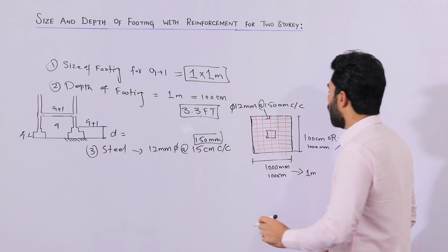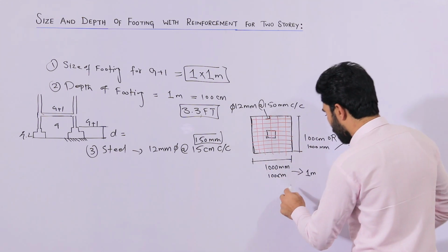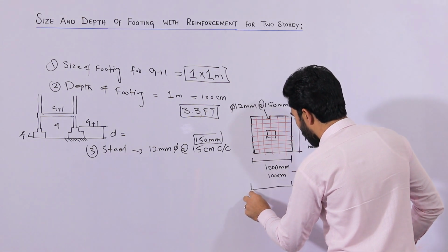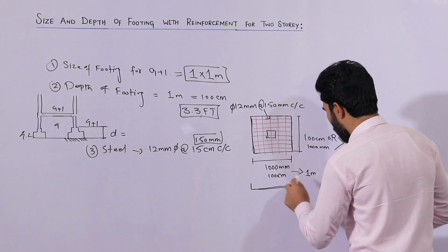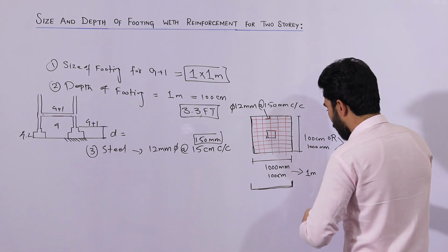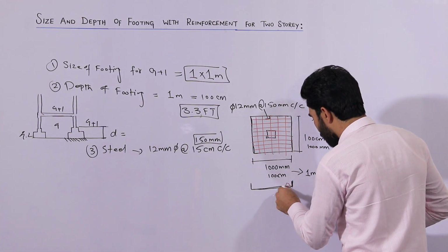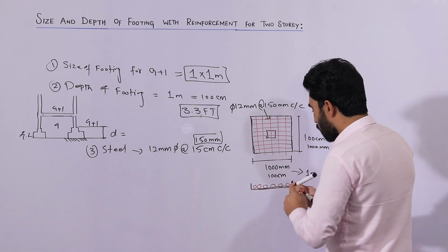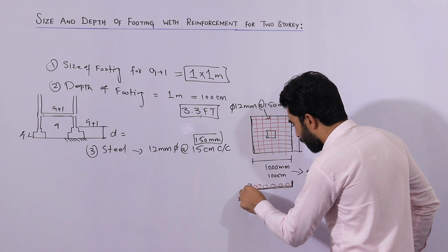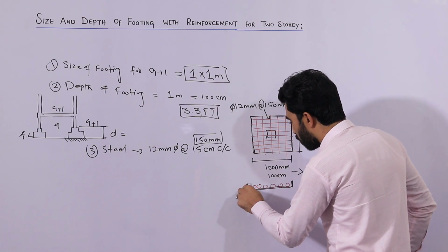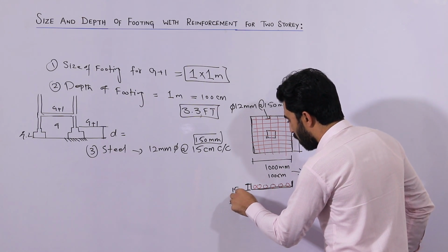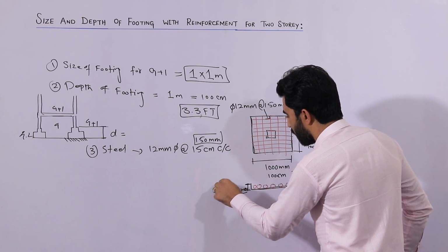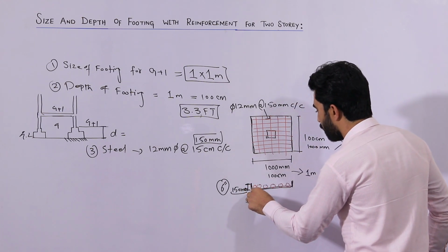Remember guys, here let me make its section, you can see. So this is its section. These are steel reinforcement. The hooks should be provided here, this hook. It should also not be less than 150 mm, about 6 inches you can say. So these hooks should be provided.